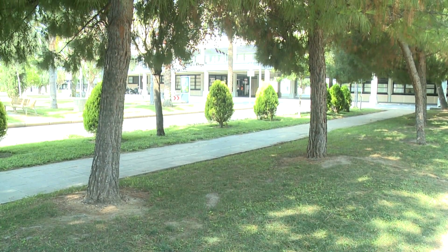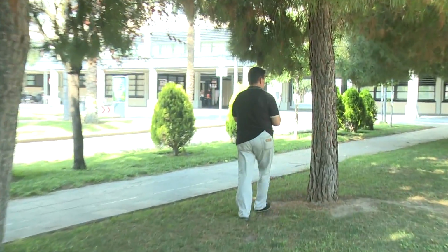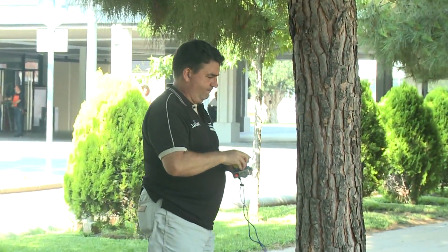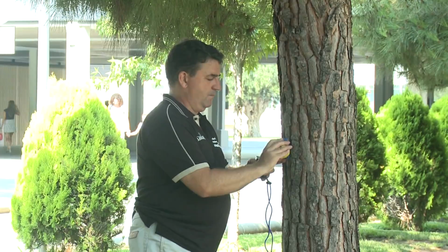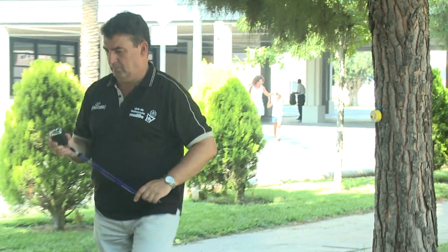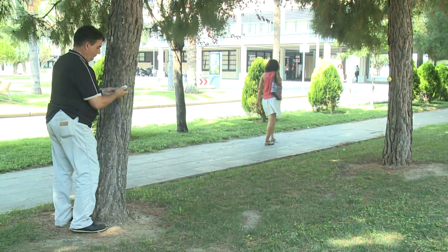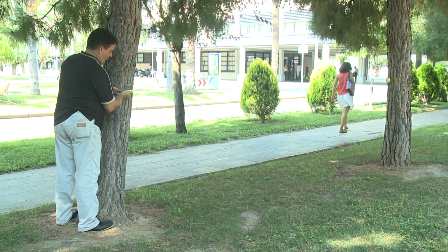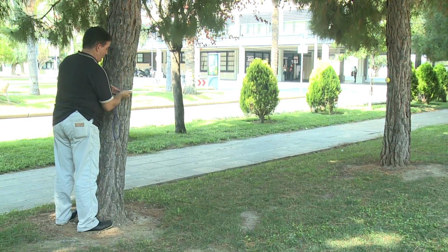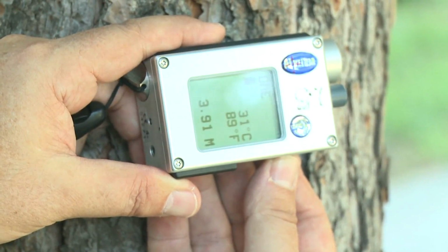Finally, we may need to describe the distance between trees on a line set or on a surrounding area of a street or park plantation. With the measurer set at the first tree and facing the transponder set on the bark of the next tree, we may measure the real distance or the horizontal distance by the rangefinder.